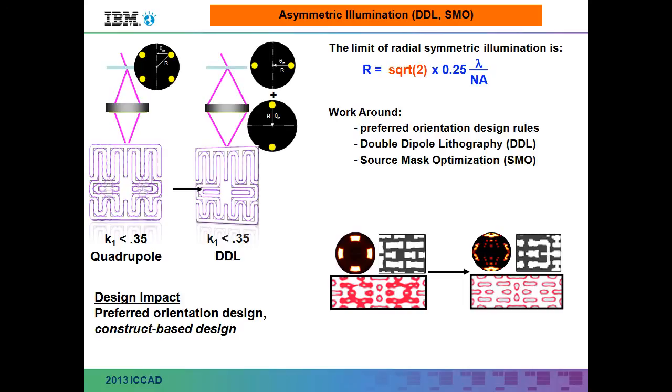So the way we solve that is to just make continuous lines and then come back with a cut mask and form the line ends. So when we're saying single orientation, that includes line ends, right? So a fairly limited set of mask levels where that trick works. The other idea of, if the designers come back and say, first metal has to be bidirectional, I can't figure out how to make it unidirectional, we say, okay, well, do 2 exposures, right?